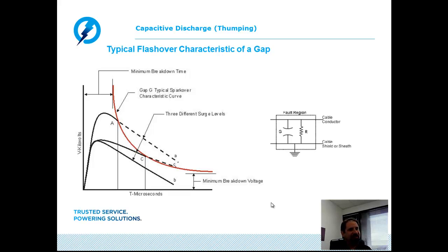Now, if you were able to follow along in those examples, that really depicts the major differences between one thumper and another. Again, size and weight are going to be very big considerations when taking a thumper out onto a job. But remember, sometimes with smaller, lighter weight and portability, the sacrifice may be a smaller capacitor inside that thumper, and in essence lower energy produced as a result.